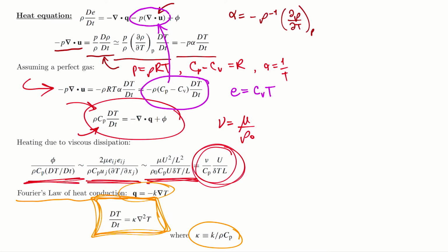So in summary, the Boussinesq approximation applies, like we said, in cases where the Mach number is small, we're not considering propagation of sound or shock waves, the vertical scale of the flow is not too large, and the temperature differences in the flow are small. Then the density can be treated as a constant in the continuity and momentum equations, except in the gravity term. Properties of the fluids like mu and K and Cp are also assumed constant in this approximation.